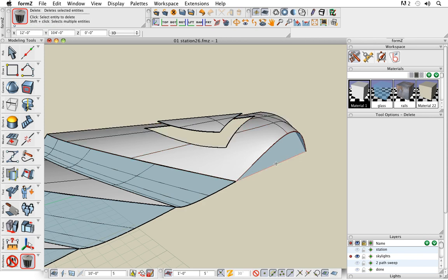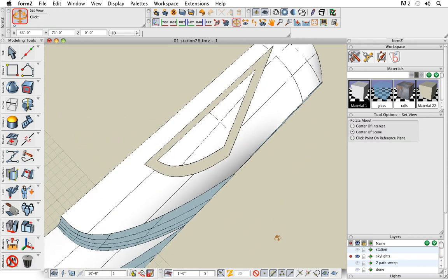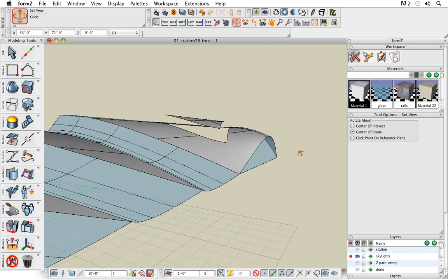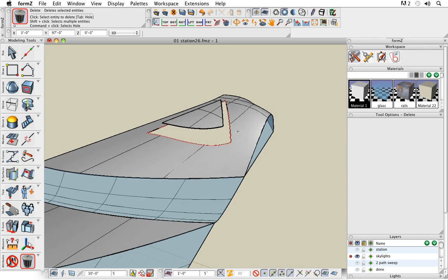And we end up with just that outside section. So we use that to cut the profile. And you can see it's a little bit larger than the original skylight shape. Okay, so now what we need to do is create a nice transition that goes from the edge of this opening that's in this object up into the top of the skylight surface that we have.